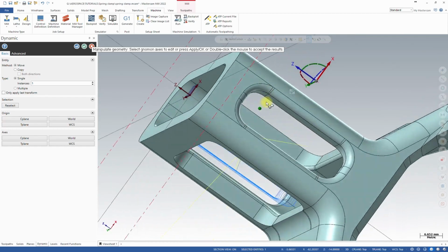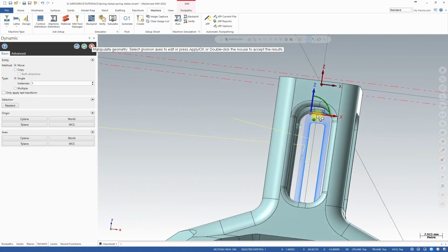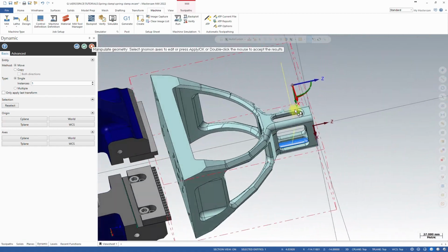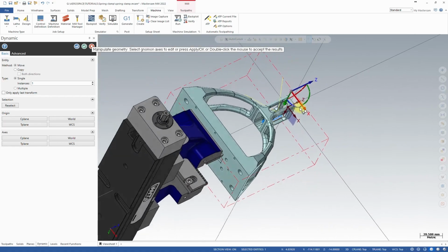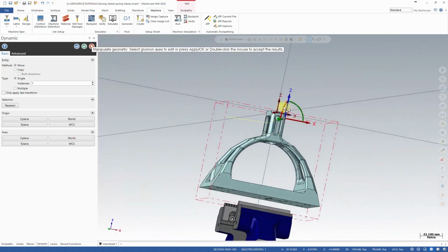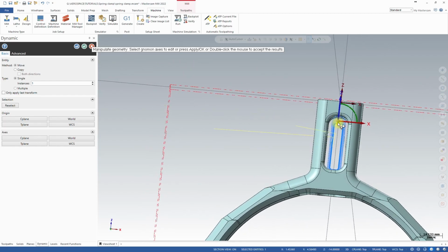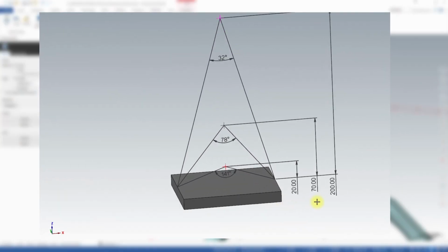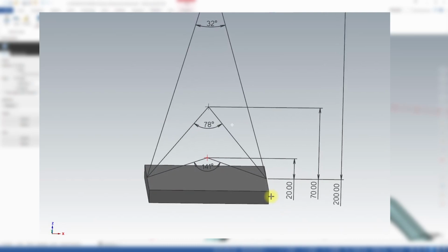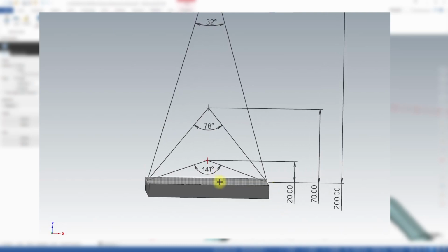And if you control your tool axis from point, as a simple rule, the farther you are away from the machining surface with this point, the smaller angular changes you will get. The easiest way is to show you, to explain how this tool axis control from point works.